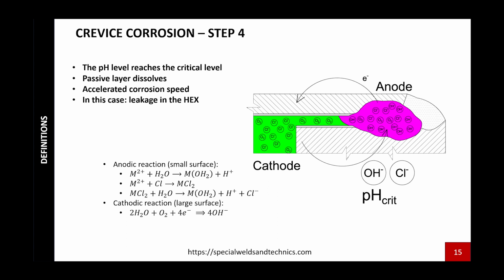Usually we use the same throat thickness for the welding joint as the tube thickness, but if you have ever seen a microsection of a tube-to-tube sheet joint, you can see the welding joint is always bigger than the tube thickness. So 99%, if the filler material is matched for the base materials, the corrosion damage is going to be on the tube first.